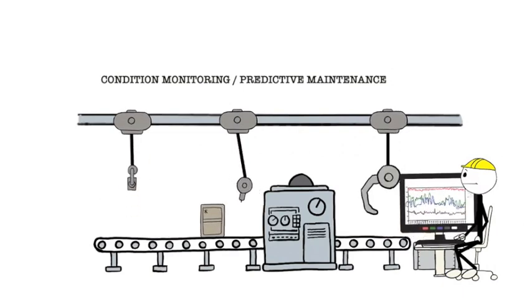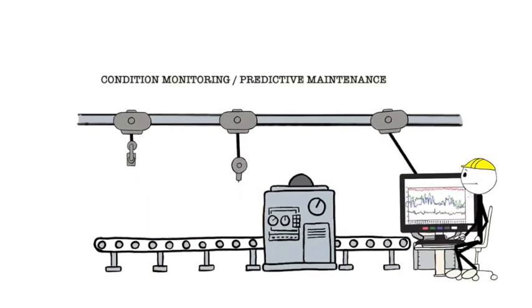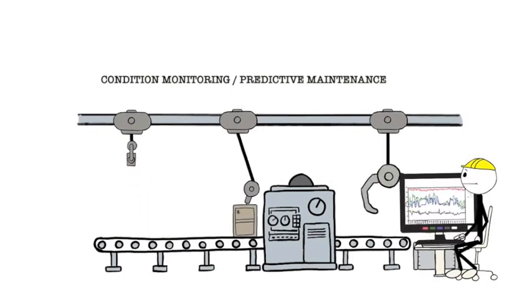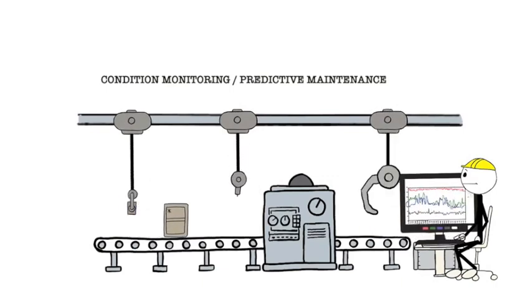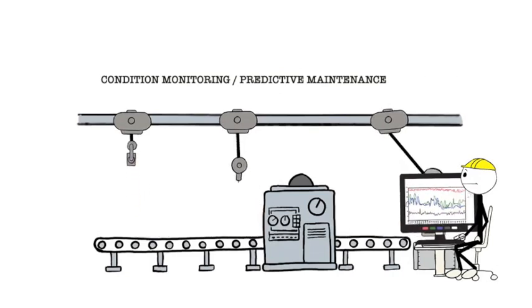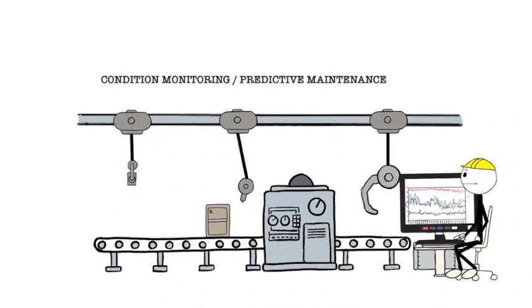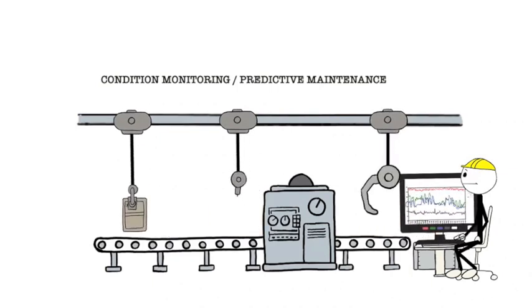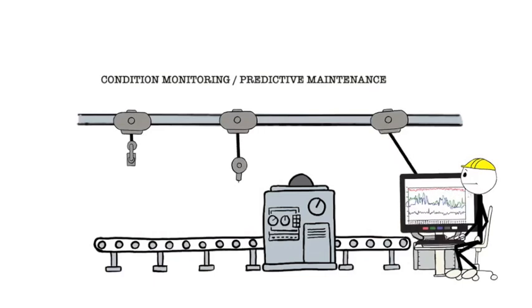To do this, we must monitor key sensors such as temperature, vibration, flow, deterioration, usage, looking for indications of failure, and using these and indicators from other equipment, either on your plant or others, to give a greater knowledge of what is happening in order to predict when a failure may occur. The more intelligence we can gather, the better. And these days, more and more equipment comes pre-built with control and instrumentation sensors and may be connected to the internet. The term is Internet of Things, to enable the intelligence we gather to better manage the plant.